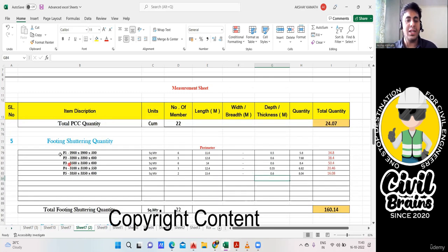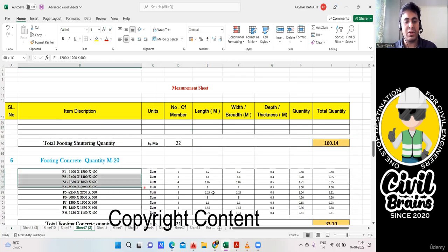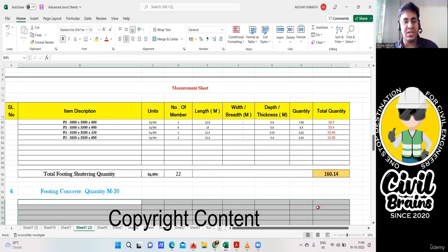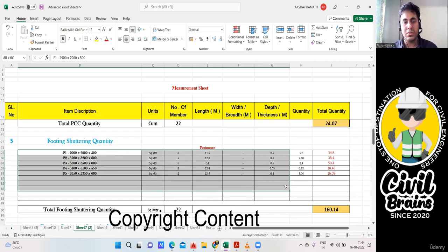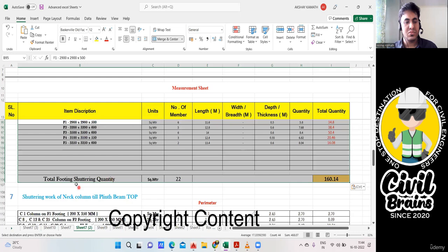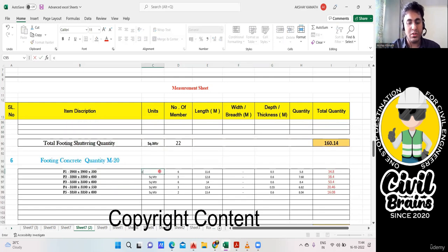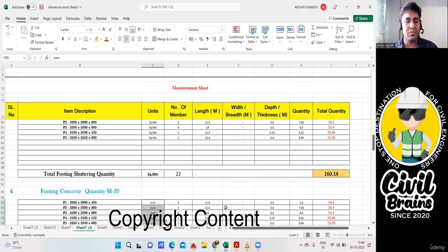Now coming to the footing concrete quantity. Again copy the same thing. First let me delete this total footing shuttering quantity. I'll delete this part and we'll copy this part. And this is the total footing concrete quantity. This will be in cubic meter, and this also will be in cubic meter. And then just drag it. Done.